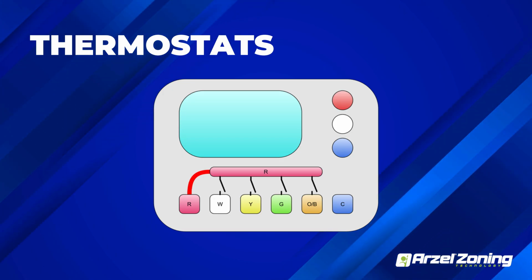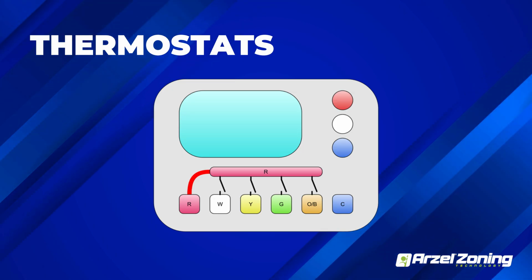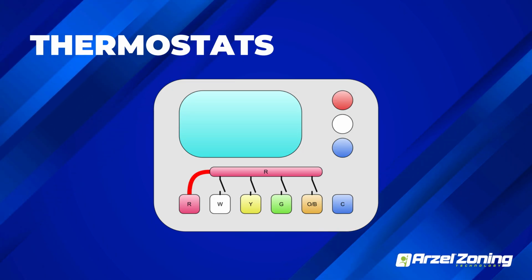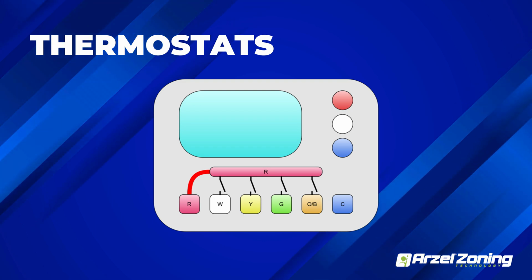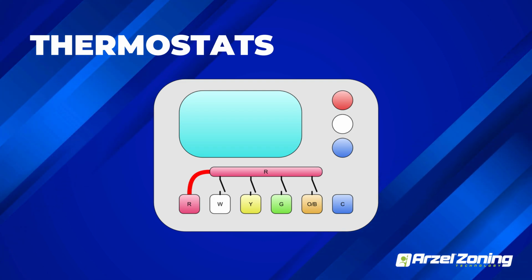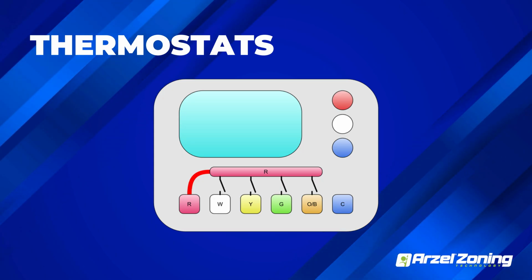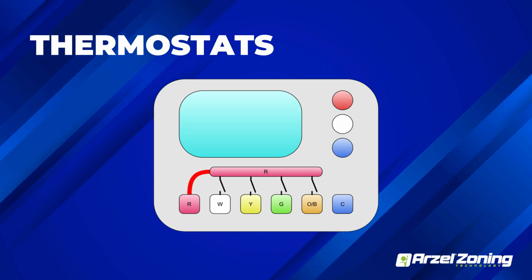So the place to start is with the thermostat. The thermostat is that starting point for all our controls. And just because the thermostat's calling for heating, just because it's calling for cooling, doesn't mean it's actually calling. And that's where we need to start our testing to verify that the thermostat is good.